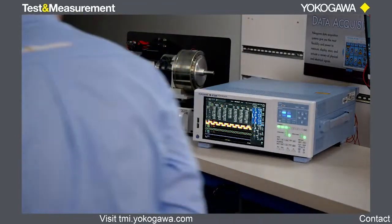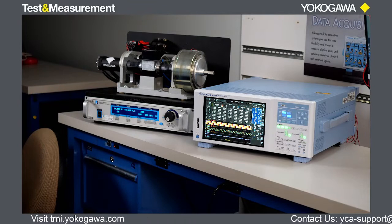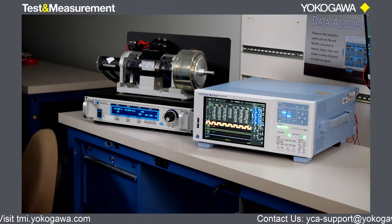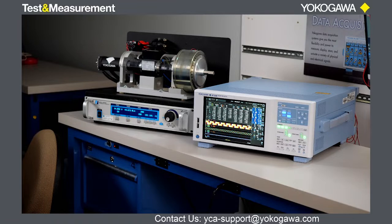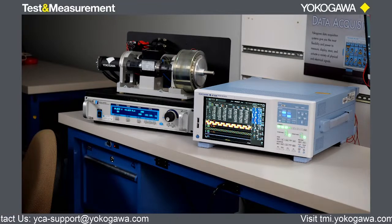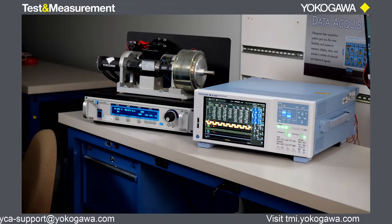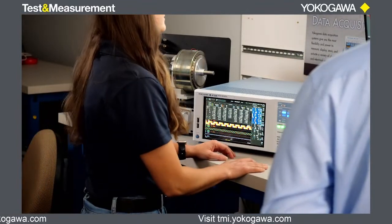Yeah. So over here where we're taking measurements from, we have a motor dyno. It is taking a DC source signal and going through an inverter and getting three-phase AC signals out of it. And then that is being run into our motor right here. And then the motor is hooked up to a brake, a hysteresis brake. That is applying a brake to keep the speed constant. And then from that we can get mechanical power out of it. So I think we're going to show the back of the WT5000 now, right? Yeah.